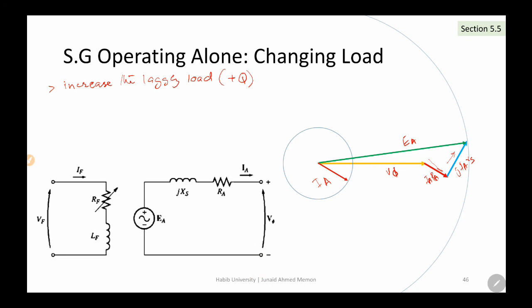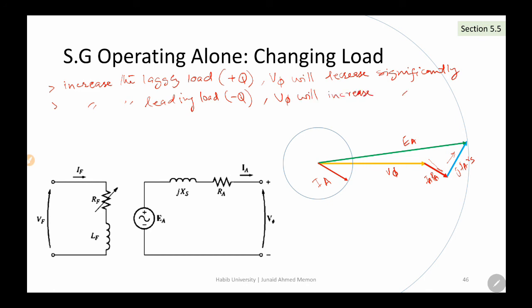It means your V phase will decrease significantly, and if we increase the leading load, it means minus Q, your V phase will increase significantly.